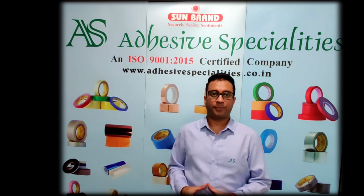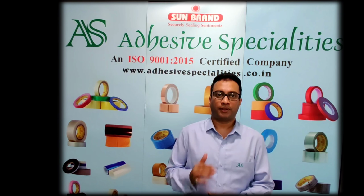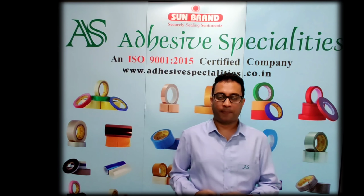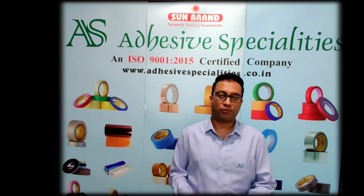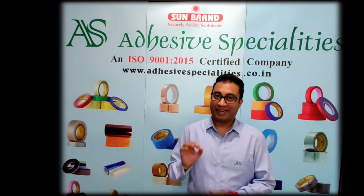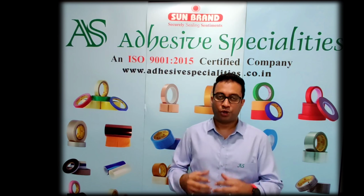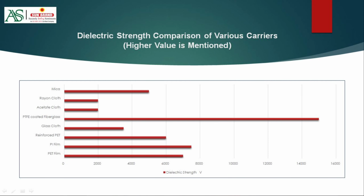Dielectric strength. Dielectric strength of the electrical tape is extremely important. The dielectric strength of a material is a measure of the electrical strength of an insulator. It is defined as the maximum voltage required to produce a dielectric breakdown through the material. In electrical tapes, the dielectric strength indicates the tape's ability to insulate and can also help compare different tapes. Tapes with higher dielectric strength values show a better quality of insulating material. In this chart, you see the dielectric strength comparison of various carriers.